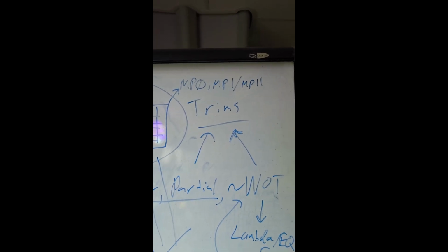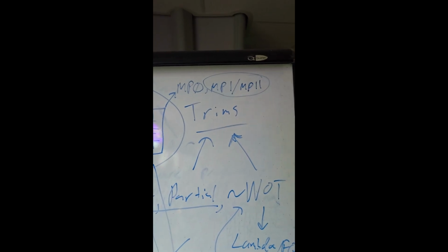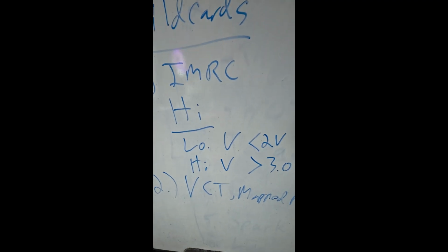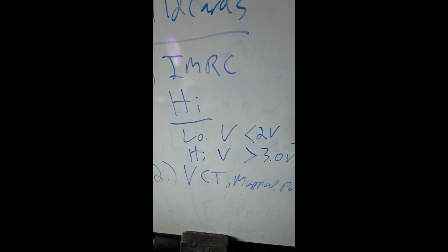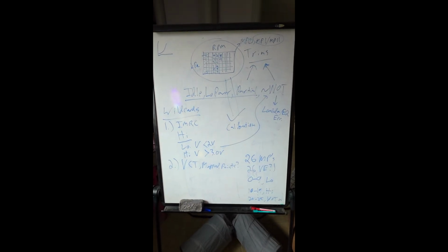And if we log efficiently, we can actually tune 2 mapped point tables at the same time if we filter on this voltage state. You're going to see what that means when I go to the software. But that is what we are up against.